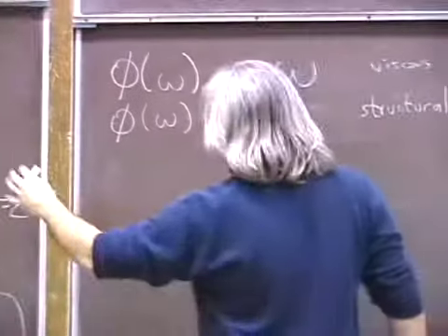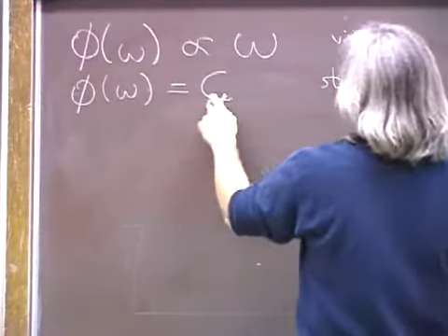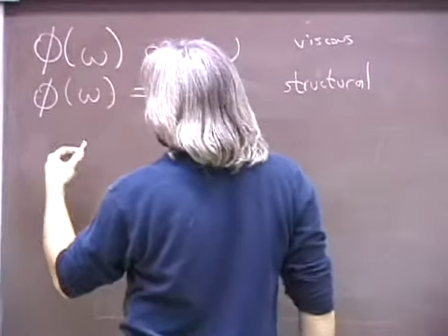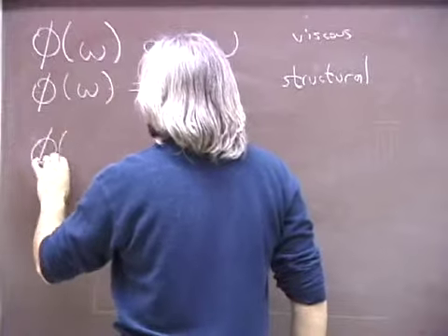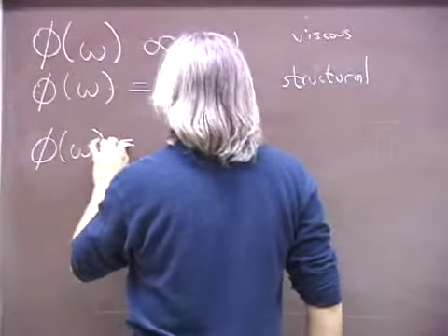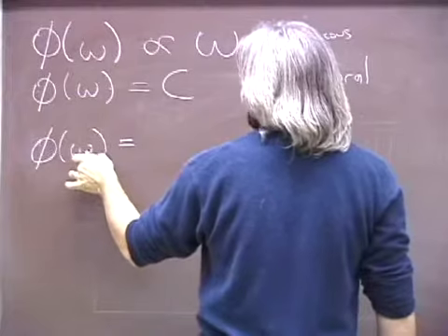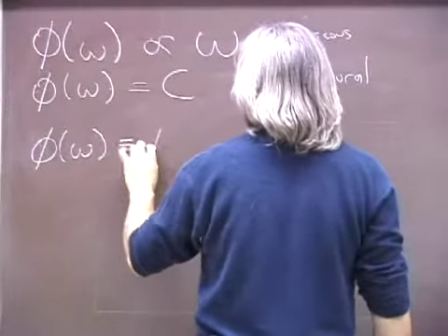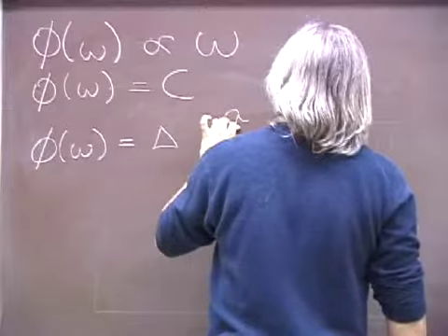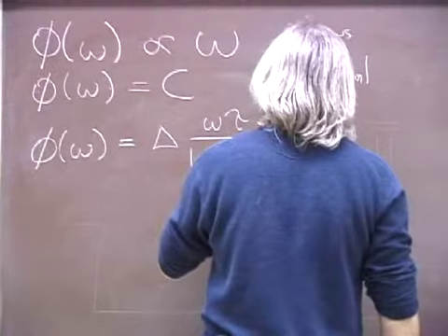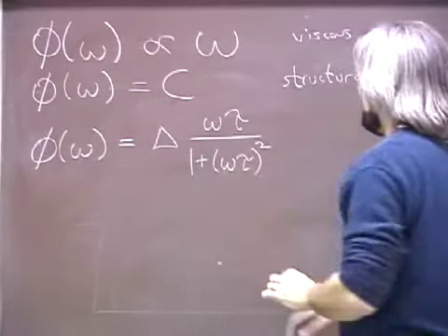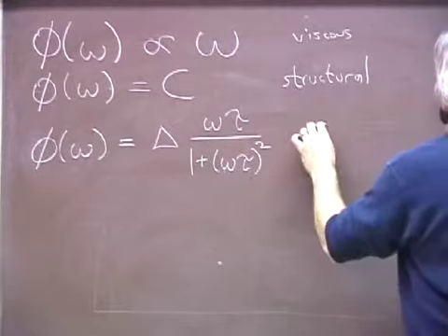Okay, viscous damping, the kind you get, for example, due to resistance from a gas. Structural damping, which seems to describe physically most damping that you see in materials. And there's also something that we could call a Debye peak, where the dissipation is given by some strength and is peaked at some frequency, which is given by a characteristic time in the system.